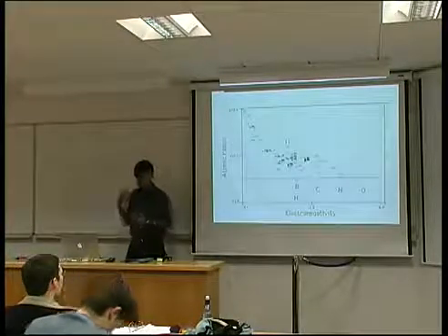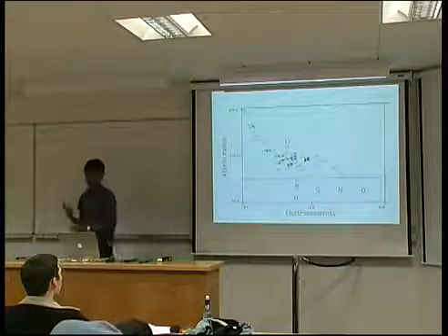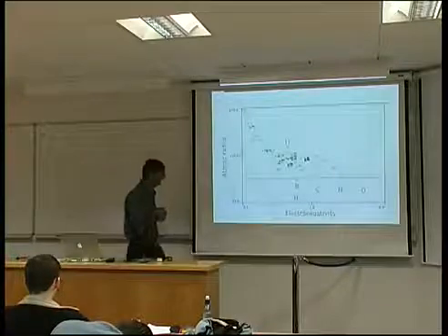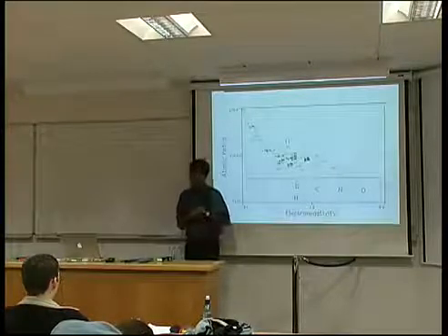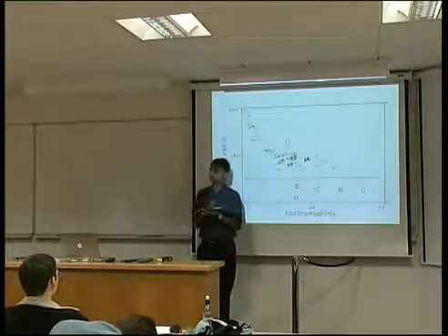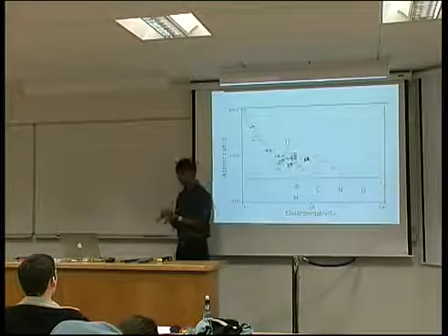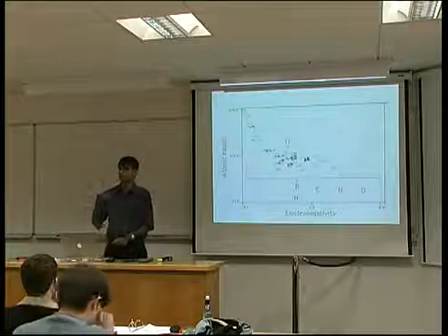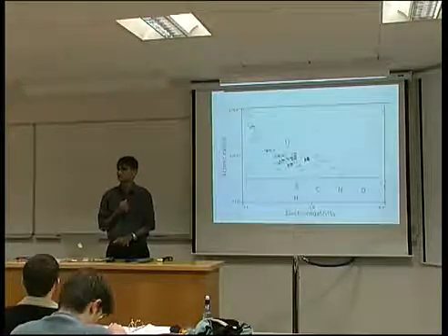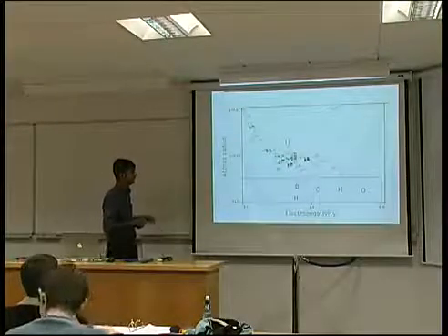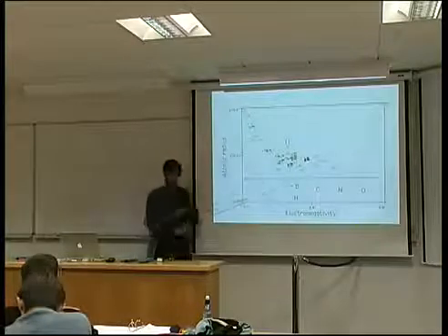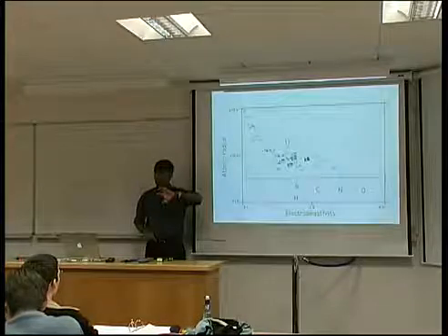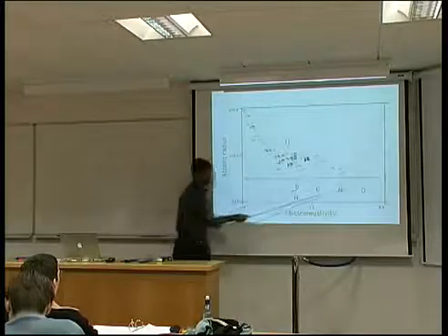Now, titanium does dissolve a very large quantity of elements, and there are some very simple rules as to whether the elements dissolve substitutionally or interstitially, and these come from the work of Hume-Rothery in Oxford back in the 1950s. If the radius of the atom is less than about 0.6 of the host atom, then the elements dissolve interstitially.